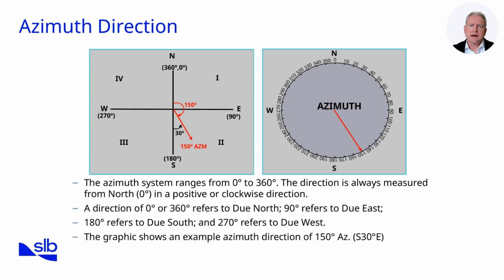So, question. I am on an azimuth bearing of 80 degrees on the compass. What would my quadrant reading be? I will give you a moment to think on it. The answer is east 10 degrees north. The reason for this is that we have gone over 45 degrees, so the easting dominates the reading and is pronounced first.